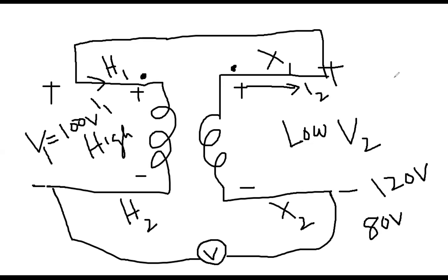Yes, yes. So therefore, I want to verify that I placed the plus and minus here correctly. Is the transformer polarity marking correct or not? That is what I'm trying to find out. And that's why I applied 100 volt here.